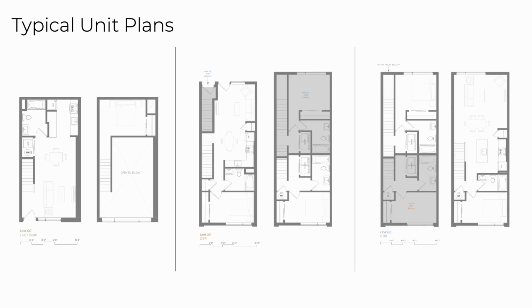These unit plans focus on stacking plumbing walls in a similar way as the proposed project does. By stacking plumbing walls, it saves money, requires less piping, and potentially eliminates roof penetrations, as I mentioned before.